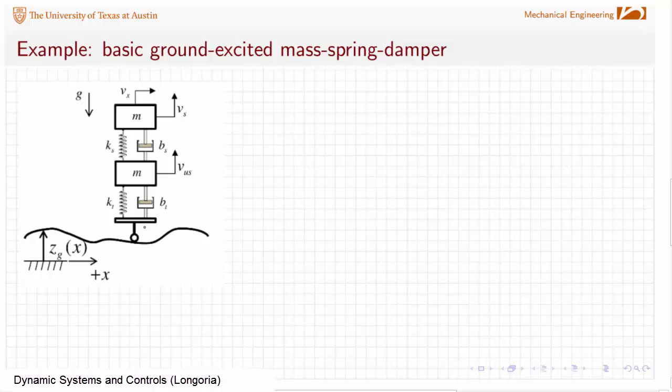The key thing, and the reason I like to introduce this problem, is that working vibration problems then becomes pretty easy, because you see this a lot where you have masses, velocity, with a distinct velocity here, distinct velocity here, and a distinct velocity here. And on all of these problems, it becomes simply a matter of throwing down ones, creating velocity differences, and then attaching spring and damper. Power always into passive elements.